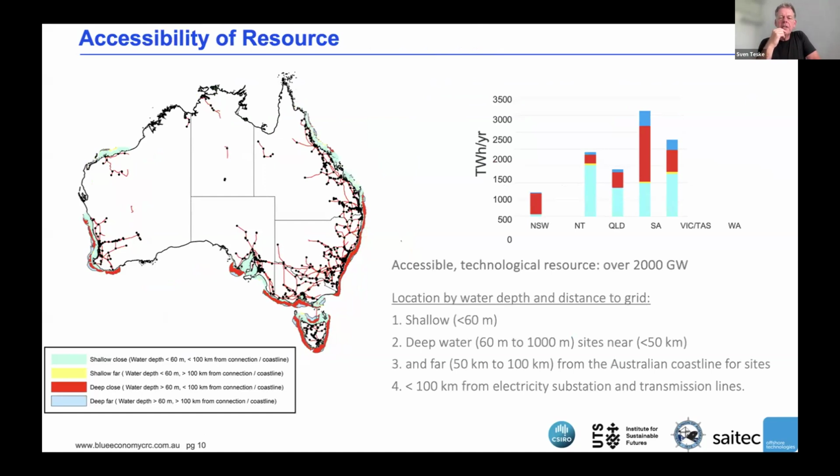The second step is the location and the water depth, as offshore wind obviously needs to be placed at sea. Currently, more than 90% of offshore wind farms are seabed fixed. So they're located in the sea, but fixed to the sea bottom. The maximum you can do right now is around 50 to 60 meters. We might be able to do a few more meters, but that is the rule of thumb. Everything deeper than 60 meters needs to be floating. But floating offshore wind also has a limit, and that is around 1,000 meters, which is already quite ambitious.